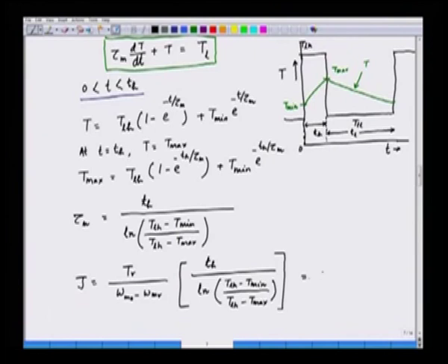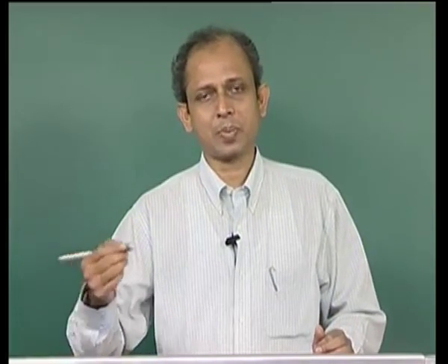and that is equal to J naught plus Jw. So, if we know the inertia of the motor, that is J naught, we can find out the inertia of the flywheel, that is Jw. Now, this is a way to find out the moment of inertia of the motor and also the flywheel. The flywheel inertia has to be calculated. The moment of inertia of the motor is known, and J is the total moment of inertia of the overall system. We can also have a similar expression if we consider the other part of the graph.